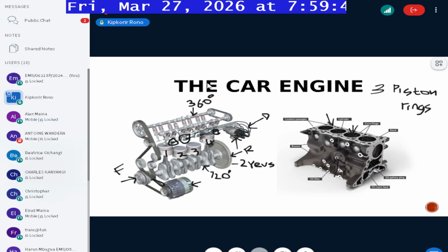It does not need to go with the cycle, because assuming, for example, that you change your air filter together with the oil, and your oil is going 15,000 kilometers, basically because it is synthetic. If you're operating in a very dusty environment, you will not have to wait to cover 15,000 kilometers in order for it to be changed. It makes no sense at all. So the air filter should always be changed according to, especially, the environment within which you're operating.